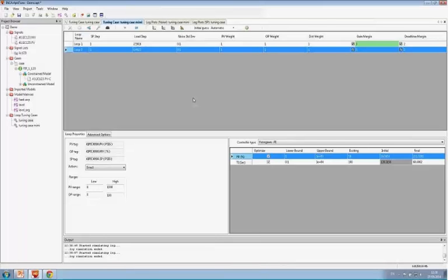We first have to tune, let's say, the state controller and make that as fast as possible, and then do a step test on the slave and tune the master. Okay. So it's a two-step method. There are some plans to support this within AptiTune in a more automatic way. Good. Yeah.